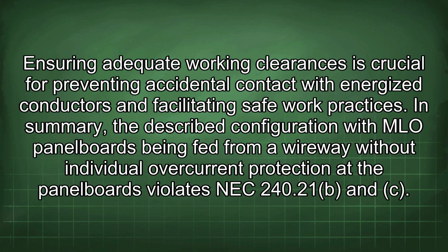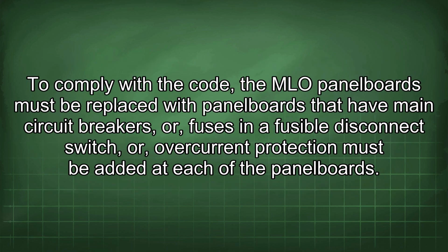In summary, the described configuration with MLO panelboards being fed from a wireway without individual overcurrent protection at the panelboards violates NEC 240.21(B) and (D). To comply with the code, the MLO panelboards must be replaced with panelboards that have main circuit breakers, or fuses and a fusible disconnect switch, or overcurrent protection must be added at each of the panelboards.